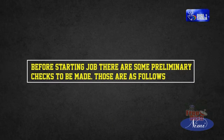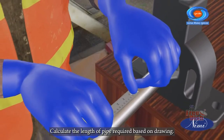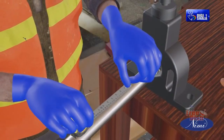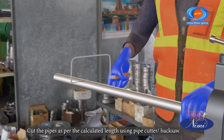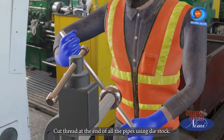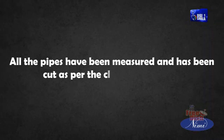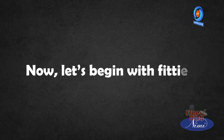Before starting the job, there are some preliminary checks to be made. Those are as follows. Calculate the length of pipe required based on the drawing. Cut the pipes as per the calculated length using a pipe cutter or hacksaw. Cut thread at the end of all the pipes using a die stock. All the pipes have been measured and cut as per the calculated length. Now, let's begin with fitting.